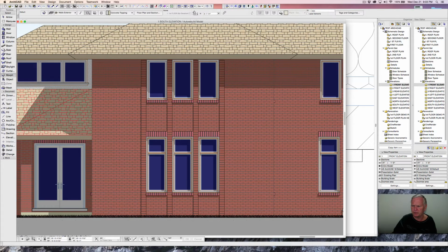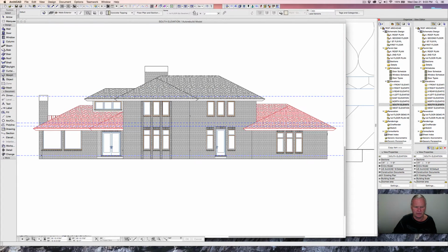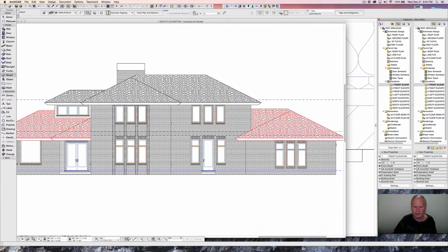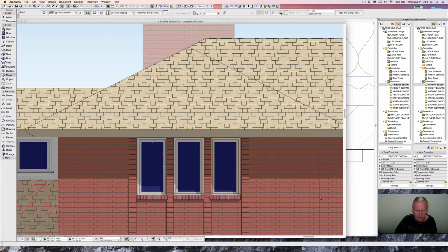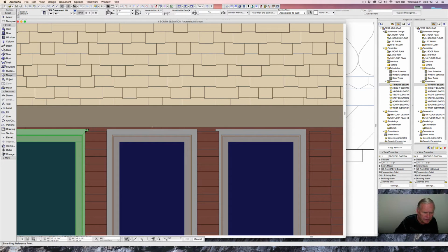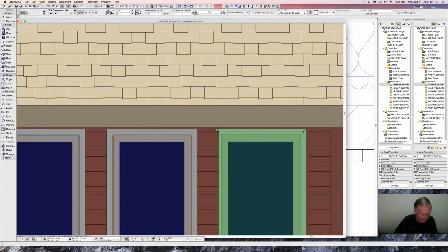And if we went to our front elevation, which I think is our south elevation, we'd see that that's lining up nicely as well, because that's just a duplicate of that. So let's go back to the front elevation, and what I want to do here is come up to these windows, and as you can see, we've got to move those windows as well because they were lined up down below. We can align them right here just by taking that brick mold point and doing a Control D over to the edge of that morph. And the same thing over here, Control D.